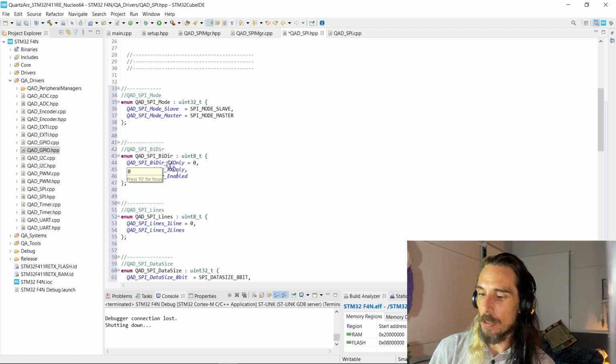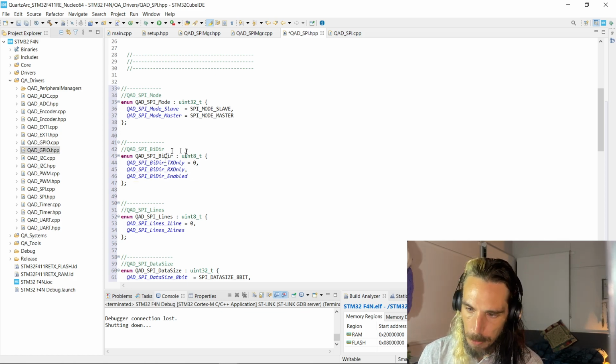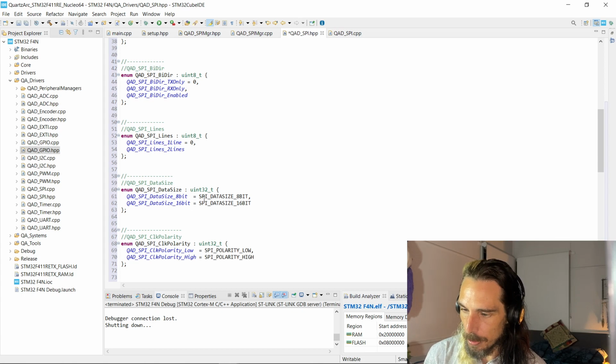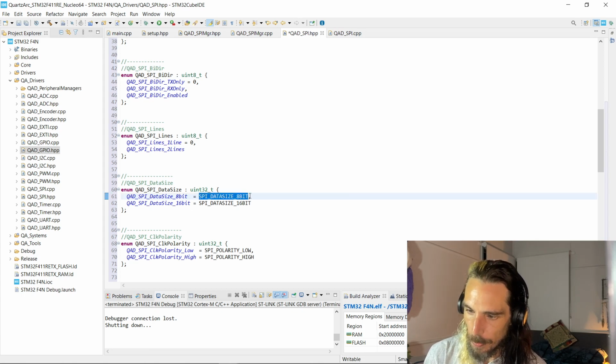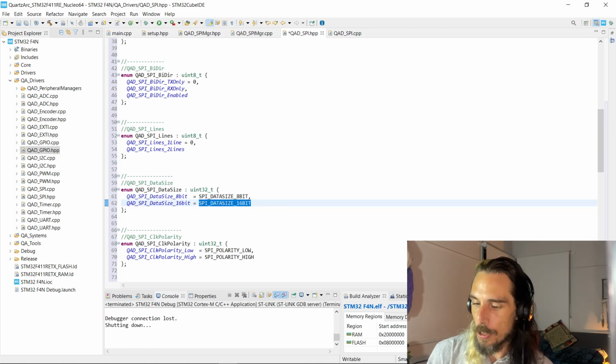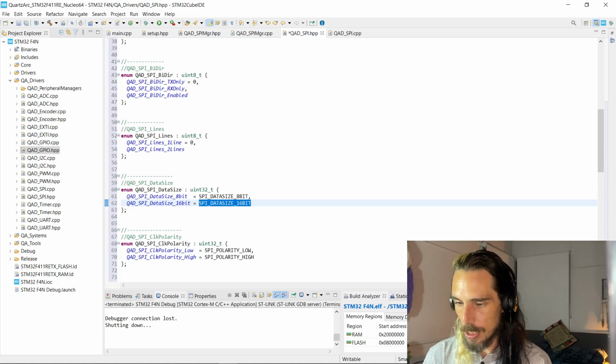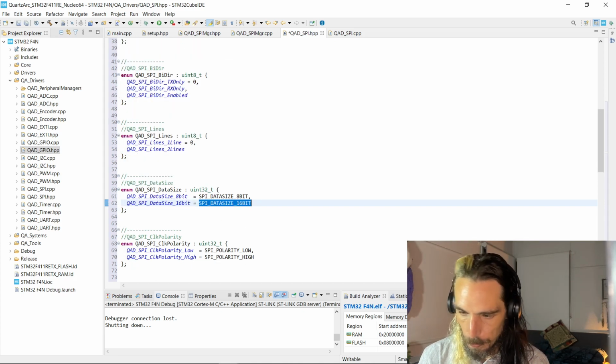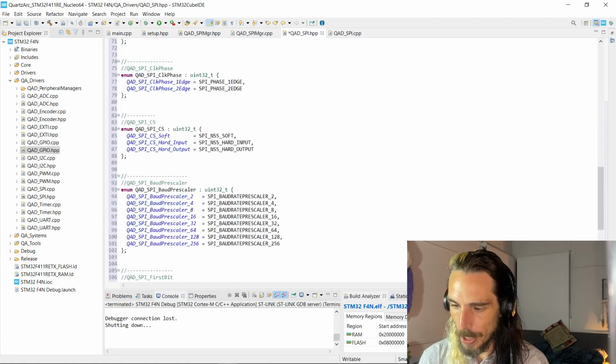So basically, when we go to initialize a particular device with a specific set of settings, we're going to be using the enums to provide those settings rather than using the HAL defines directly, so that the compiler can actually check that we're providing the correct details for each of the details that we need to provide to the driver.